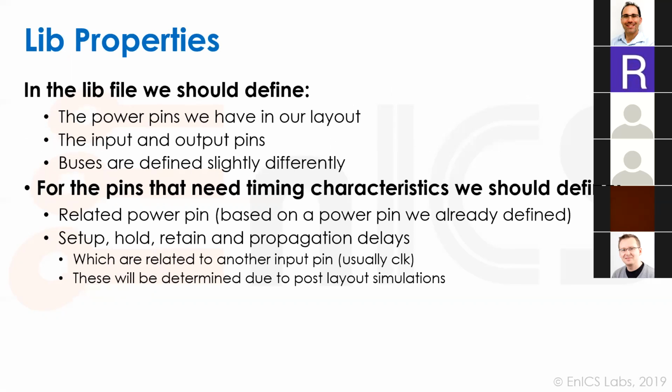What is the data retain? Sorry. Data retain is how long the data is still valid before the next clock cycle. So you have an output, and you can sample it until the data retain. The data retain is the time until it's corrupted and you can't read it out. Okay, thank you. Just to add to that, it's only relevant for things such as an SRAM where you latch the output until you maybe do some sort of pre-charge or something which will corrupt the output data. But it's not relevant in things like standard cells, so we didn't discuss it in previous courses. Okay, thank you. Yeah, that's what I wanted to say.